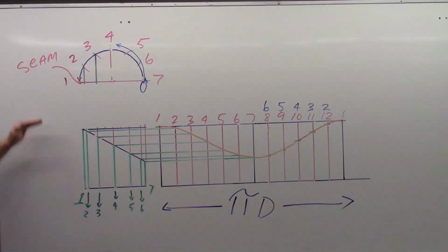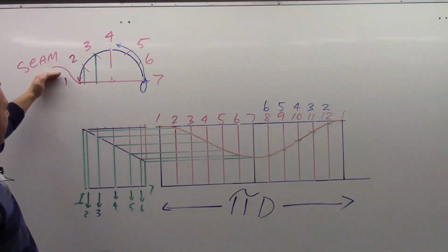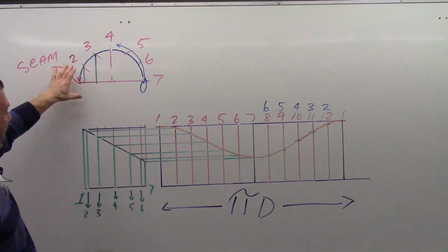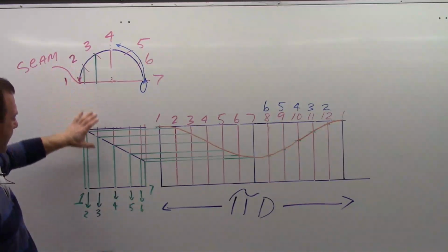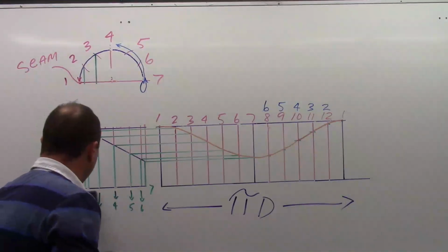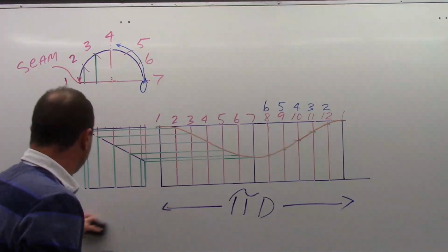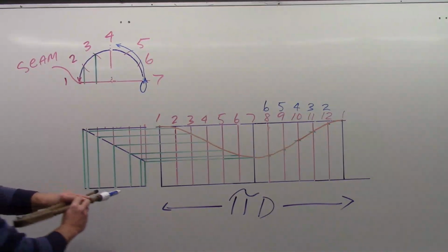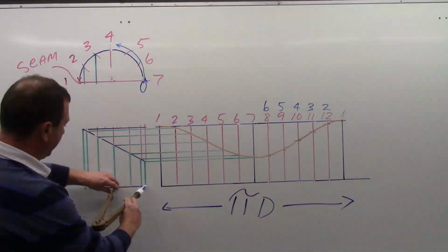Another thing we want to look at is drawing these complete views out. Now we just said that we can drop off half the plan view, and we can actually move that down into the elevation view. So I'm going to remove our numbering here for a minute. Now we said the key component that we're looking for was the height of the green lines here, where the lines hit the miter line at a specific point. So what if I put a half circle here?